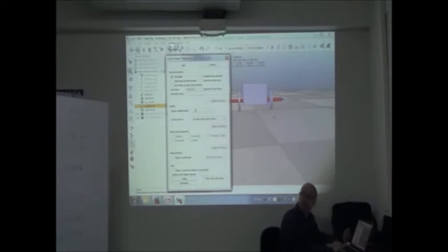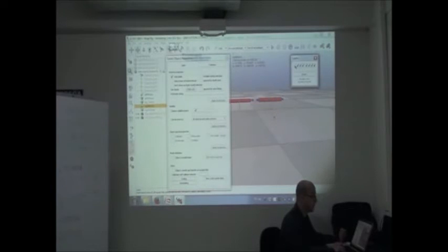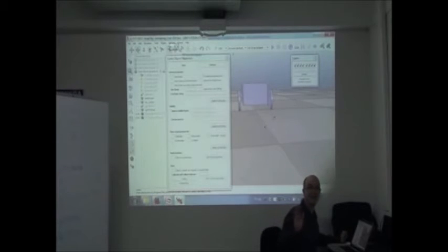And here you have a button to select which layer you want to show. So if I deselect this layer, every object that is assigned to this layer will not be visible anymore. If I invert here, I see only the stuff that is in these layers. Okay? So I don't want this to appear, so I just select and deselect it here. And same for this one. Select it here and deselect it here. Now I have this one. Is it clear for everybody? Everybody's okay? Pamela?